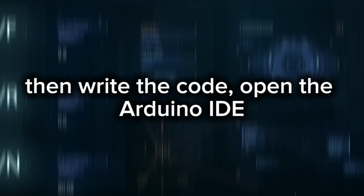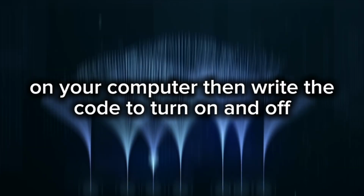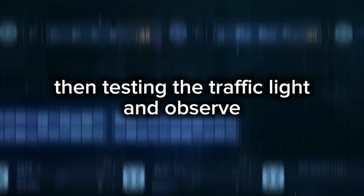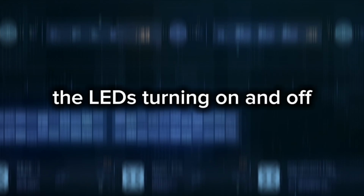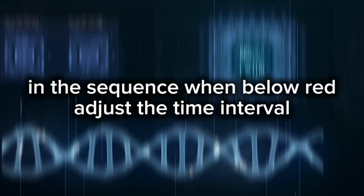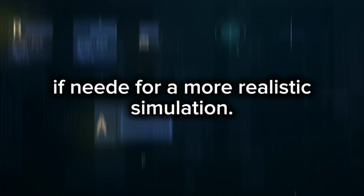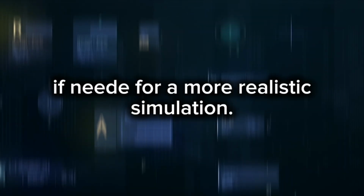And write the code. Open the Arduino IDE on your computer. Then write the code to turn on and off each LED with appropriate delays. Then test the traffic light and observe the LEDs turning on and off in a sequence: green, yellow, red. Adjust the time intervals if needed for a more realistic simulation.